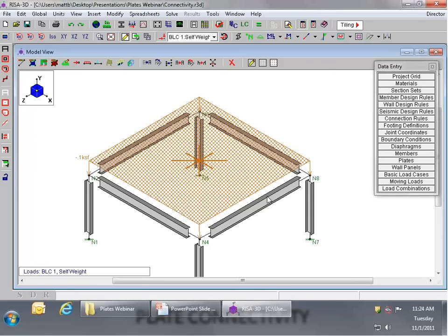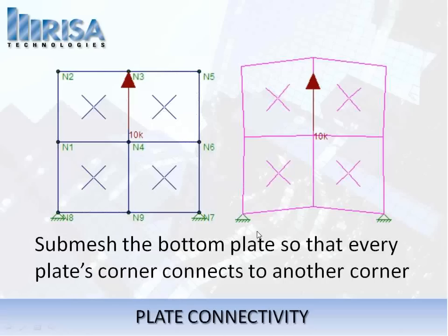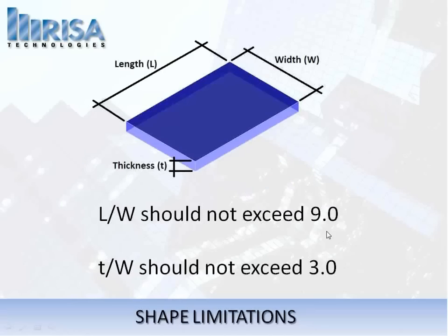So that's one thing that I definitely want to point out, is that using plates solely as a means of load attribution for gravity loading, would not recommend that at all. Let's go ahead and go back to the PowerPoint here and talk about some limitations behind using plates.